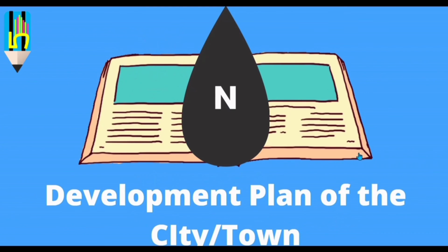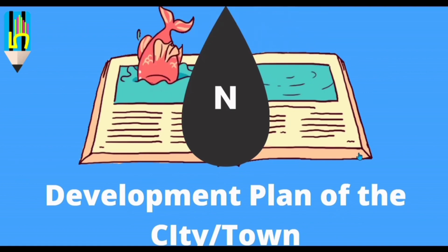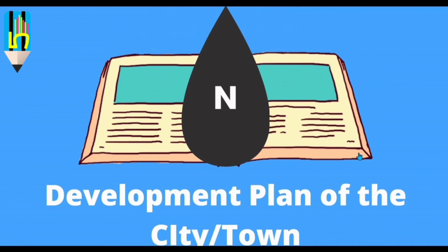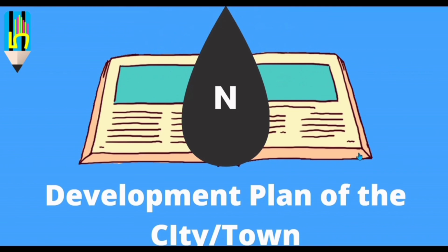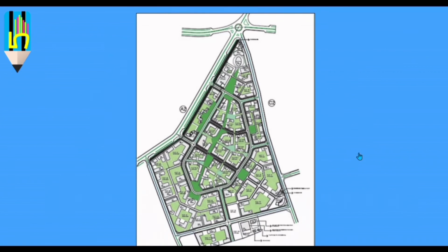The next point is the development plan of the city. Now we are designing something for 30 years and more. So we should know how the city is going to change in the next 30 years. What are the various government plans and schemes, what residential areas are going to get built, what industries are coming, and so on. This data about the development plan of the city we can get from a town planning office or an urban development office, that is, their master plan for the next 20 or 30 years. Using this we can incorporate the inputs from the development plan into our model.